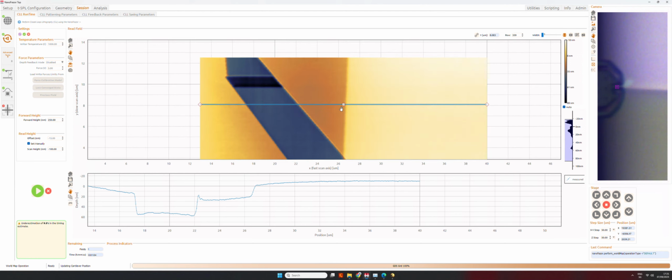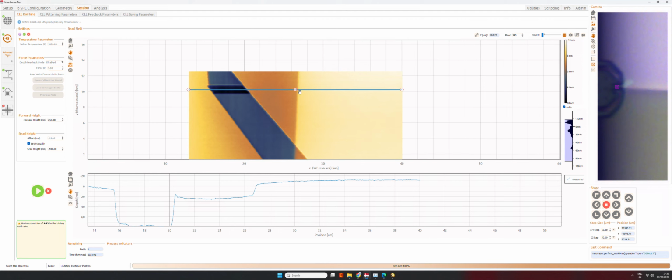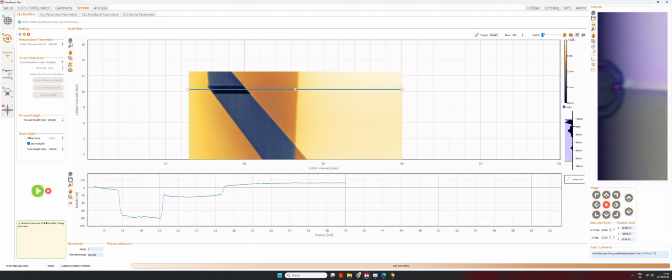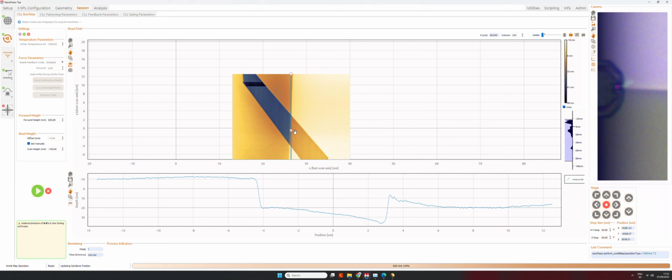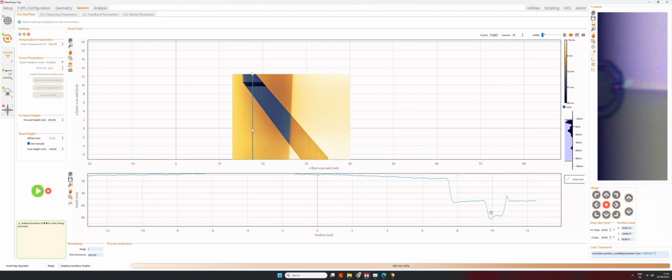We can also see the overlap between the two fields. In this case of making contact lines with the Nanofrazor, it's not really a problem if we have an overlap that causes a larger depth, because for a successful bilayer lift-off, we want to at least open the PPA mask. It's going to be problematic if we don't pattern deep enough, but deeper is usually not a problem.